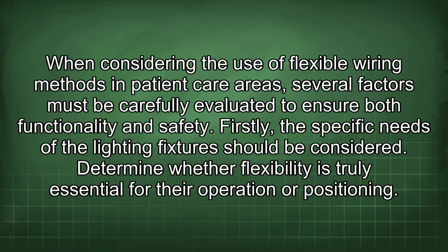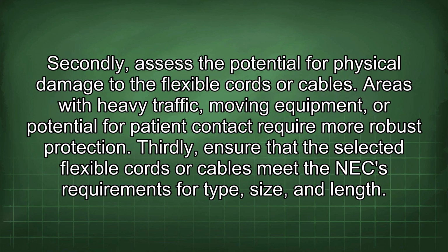When considering the use of flexible wiring methods in patient care areas, several factors must be carefully evaluated to ensure both functionality and safety. Firstly, the specific needs of the lighting fixtures should be considered. Determine whether flexibility is truly essential for their operation or positioning. Secondly, assess the potential for physical damage to the flexible cords or cables. Areas with heavy traffic, moving equipment, or potential for patient contact require more robust protection.